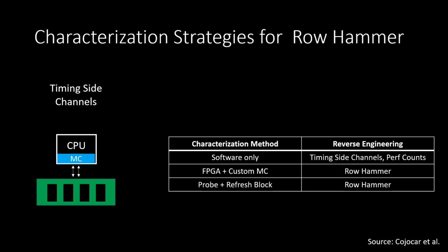Beyond this type of strategy, there is this idea of using customized memory controllers where you can control the refresh rate, where you can disable the targeted row refresh, and sort of understand the substrate level vulnerability better. Right? So by reducing the refresh rate, we can improve the effectiveness of row hammer. Row hammer becomes more visible. We use it to reverse engineer the mapping and kind of go in this loop where we make row hammer attack better and better by understanding the internal mapping.